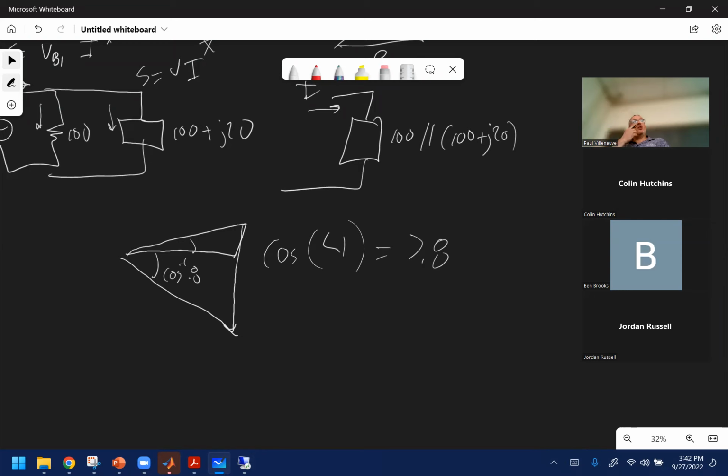So really what I'm trying to assess is, do you understand drawing the power triangle and putting the power factor correction on there? What are you ultimately trying to do? If you had drawn this little triangle and shown this, I still give people a boatload of credit if they did improve it to 0.8 leading. So it's not like I gave folks 0, but to get full credit, you just said there's no capacitor necessary. Okay. Any other discussion on that?